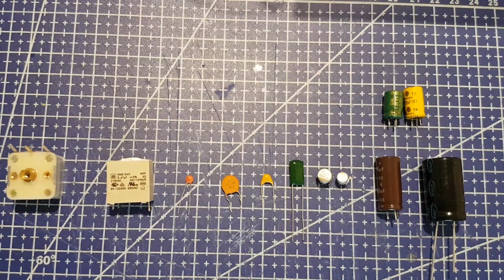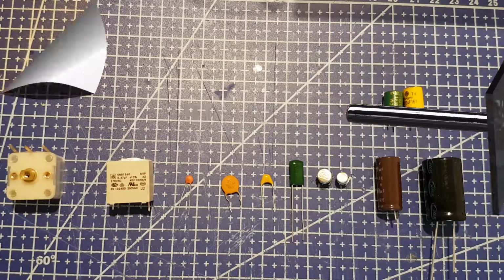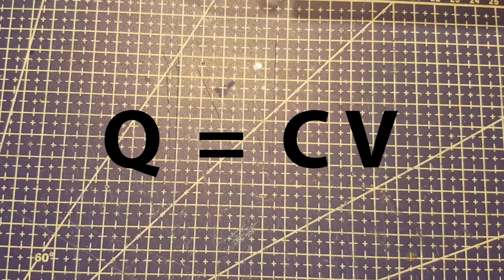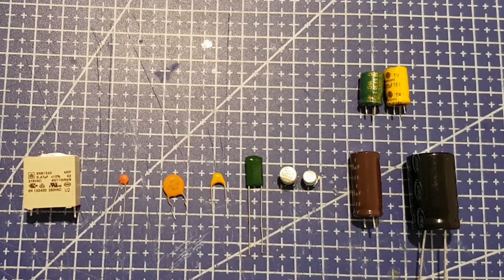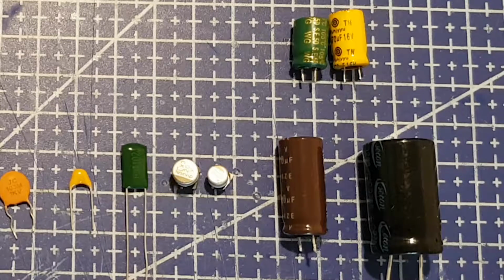So what is a capacitor? As the name suggests, it has the capacity to hold an electric charge, and this is achieved by sandwiching a dielectric material between two conductive plates, and the bigger the surface area of the plates, the bigger the charge that can be held. The charge of the capacitor, Q, is equal to the capacity, C, multiplied by the voltage, V. As you've probably noticed, most capacitors are cylindrical, and therefore you might be wondering, how are these metal plates in a cylindrical object?